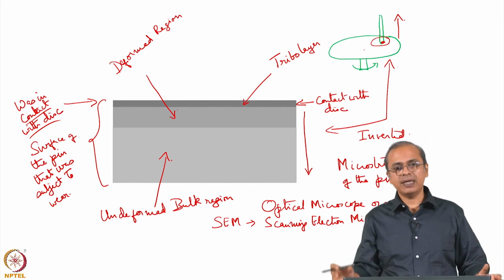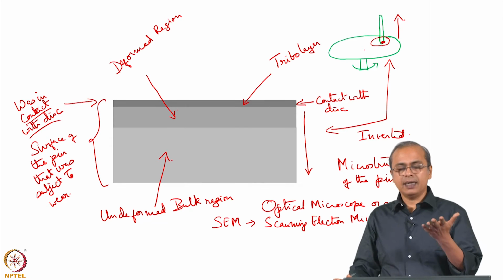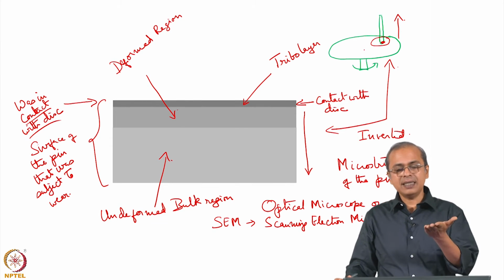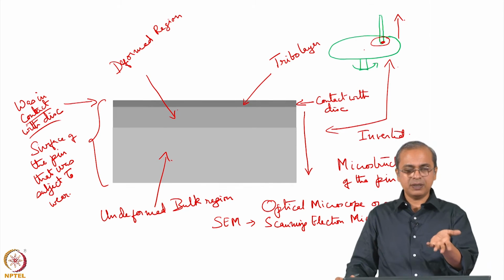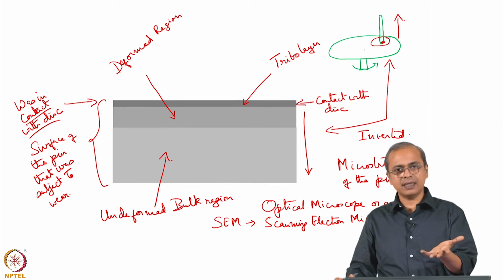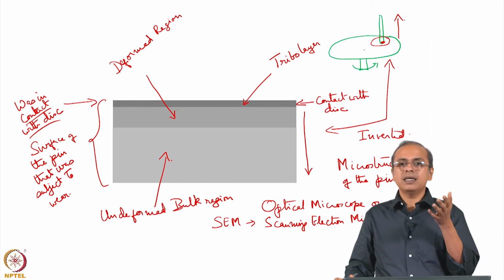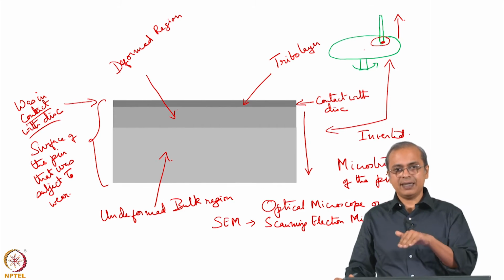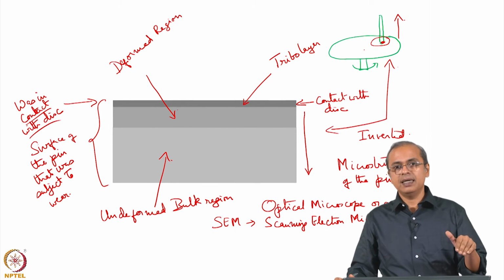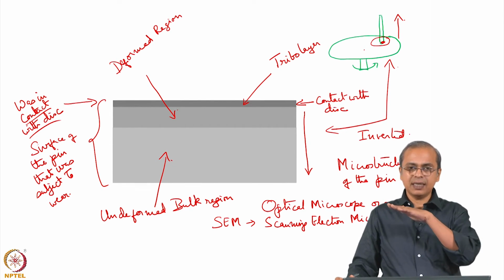So, for example, if you take stainless steel, the reason it is, let us say, resistant to rusting. When you take stainless steel and you use it, it does not rust, and that is why we call it stainless steel. The reason it is like that is because there is a chromium oxide layer that is formed on the surface of that steel, and that chromium oxide layer is a continuous layer.